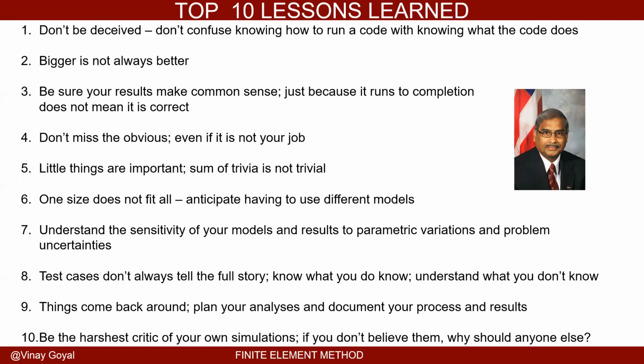which we don't understand. We want to review what happened to that analysis. So don't throw away anything you have done. And finally, be the harshest critic of your own simulations. If you don't believe them, why should anybody else? Your null hypothesis, once you finish the analysis, is that this answer is wrong.